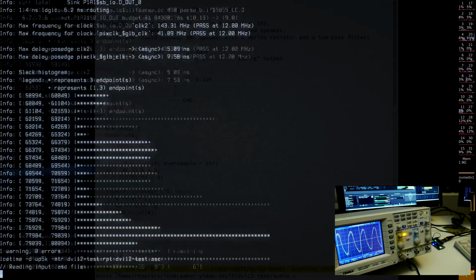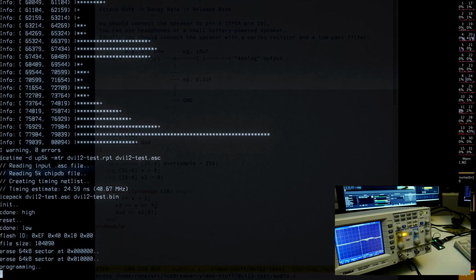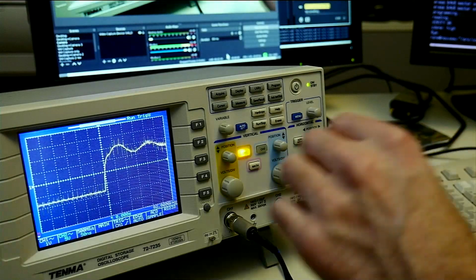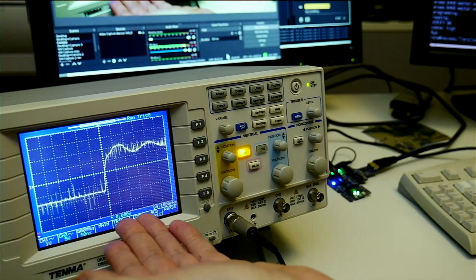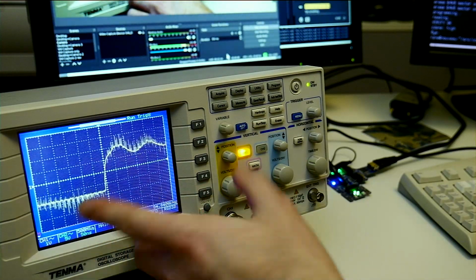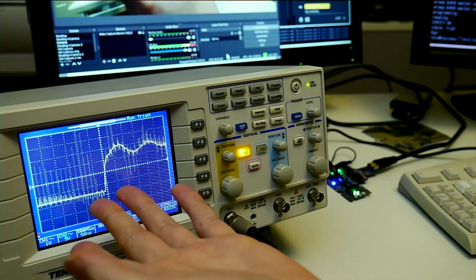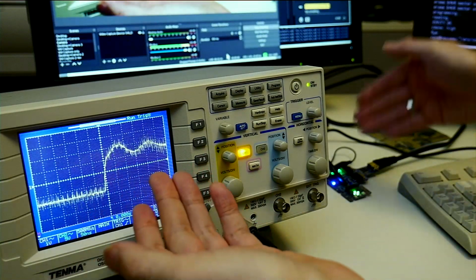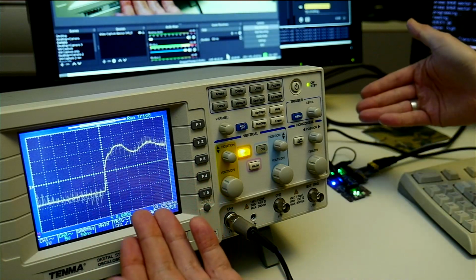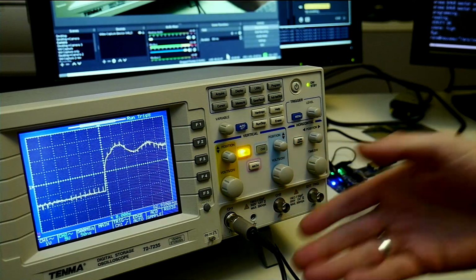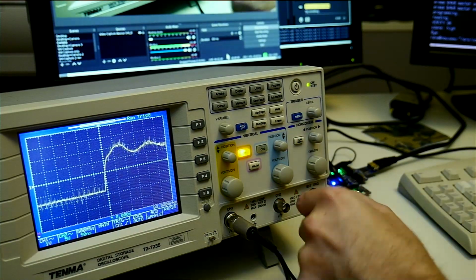And this is also why, right now we synthesize the VGA design, so it's also outputting the HDMI signal here that we are not taking a look at right now. But now you see this changed with this reprogramming, and again still not square. Also, by the way, not sure if this cable is just bad. This high frequency stuff could be some interference of HDMI and the FPGA clock, not sure, or it could be that these cables are also garbage.